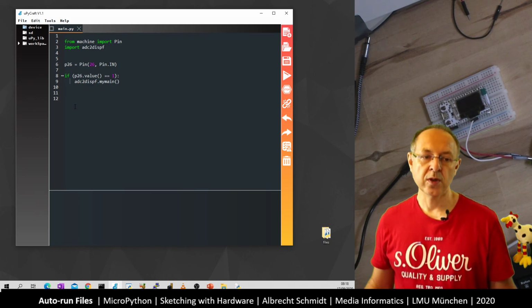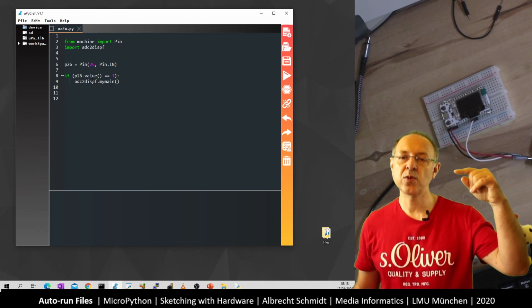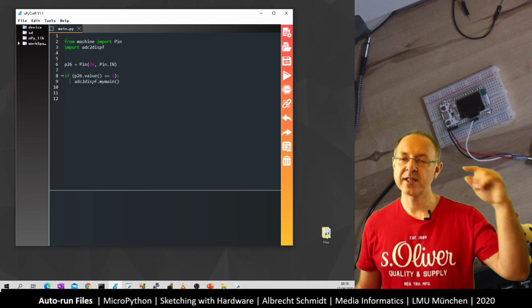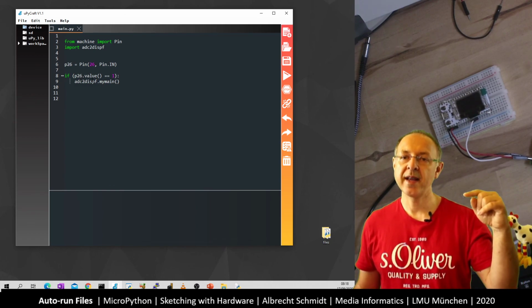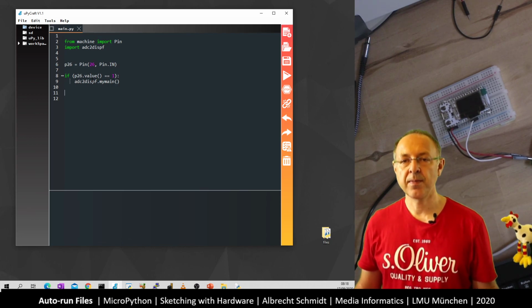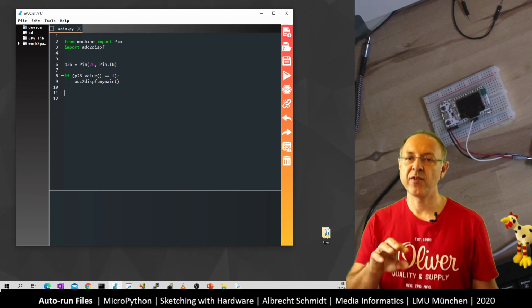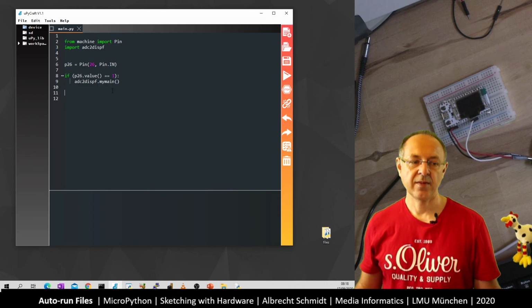So the way it's booting, it calls first the internal stuff, then it calls boot.py, and after boot.py it calls main, and you should put your code which is called somewhere else and call it from the main function. And with this we're good here.